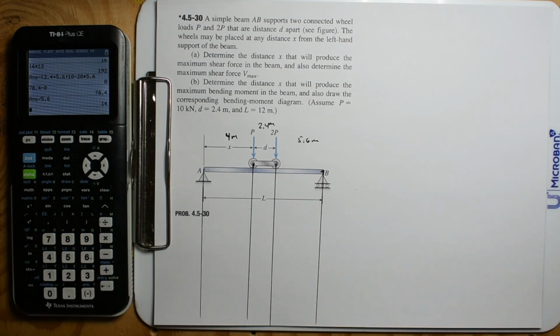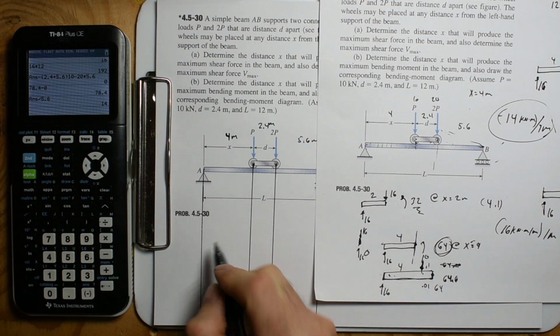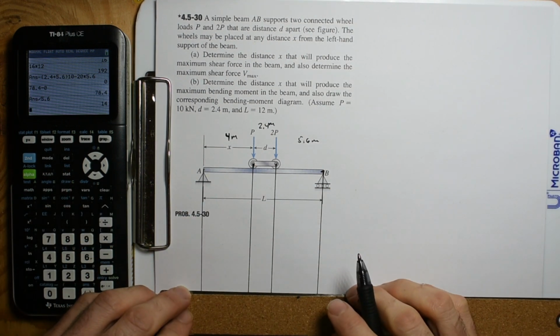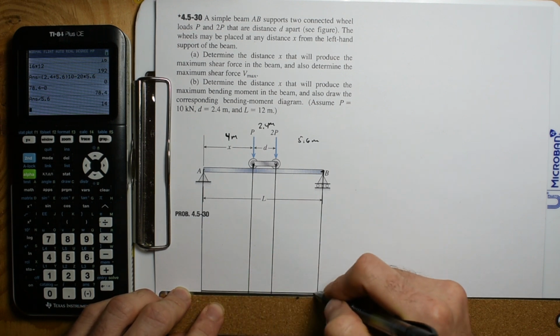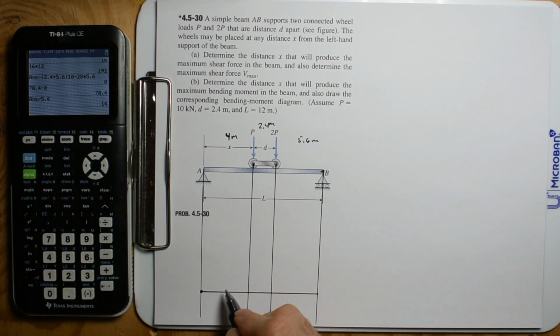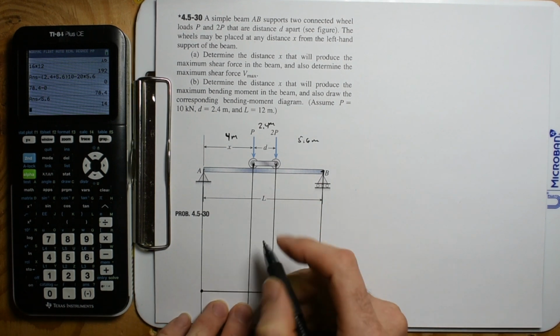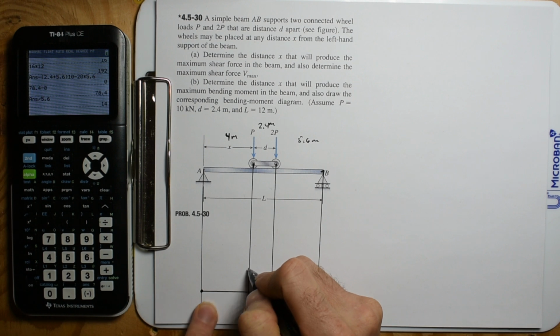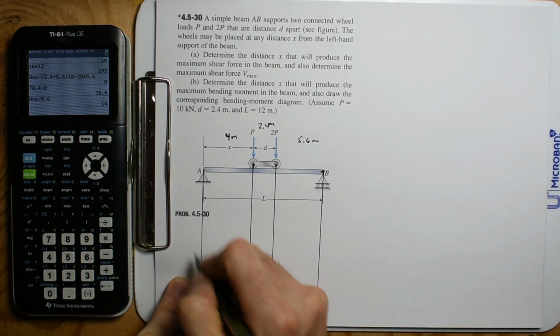All right, so now we're going to do our moment diagram. I'm going to move it down here because maybe we want to do the shear diagram the same way. So here's our moment diagram. We're going to start at 0, and it's all going to be a positive moment, the entire thing. We're going to go up to 64, and up to a total of almost 80.